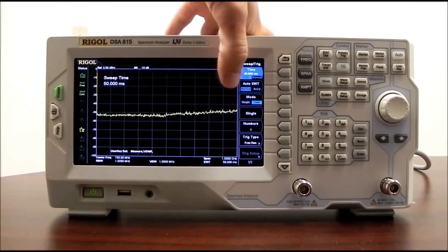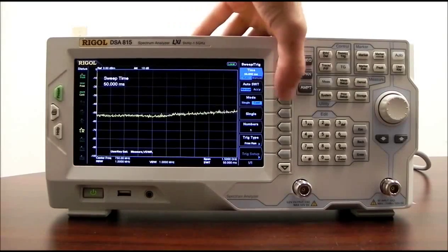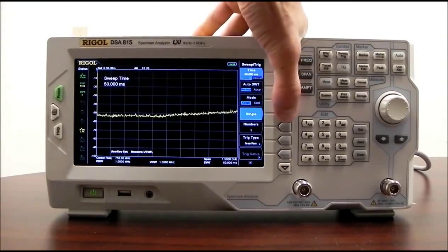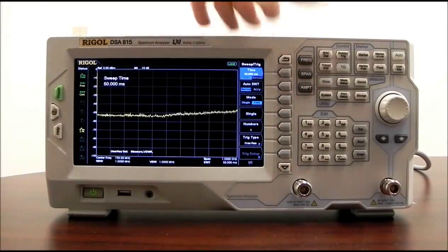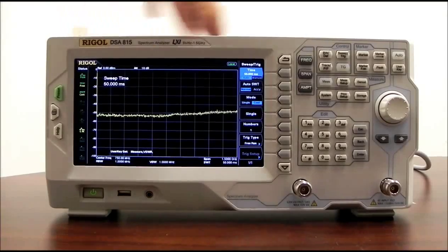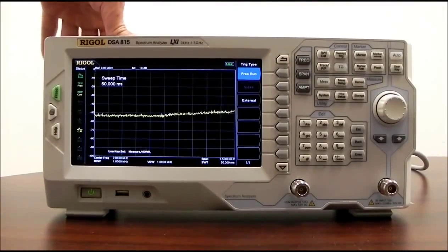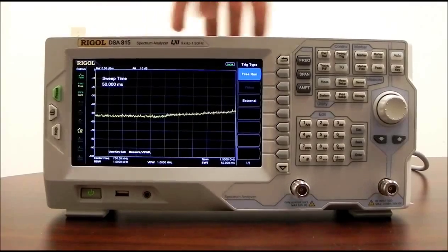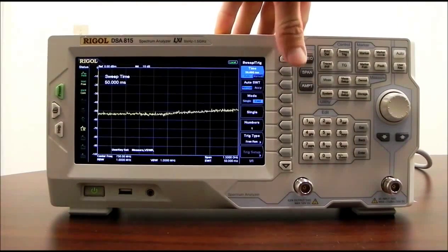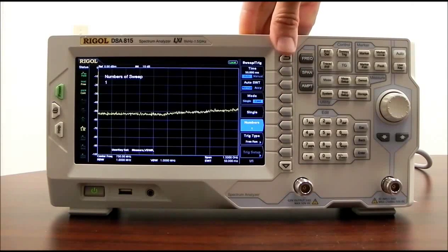We have auto sweep time. We want to keep that normal, or we can go to accuracy mode, and then for mode we can go continuous or we can go single, and with single we can just press single trigger if we wanted to capture one image. We also have the ability to do an internal trigger, which is going to be free run, but we can also do external. There is a BNC connector on the back, a TTL level signal, so if you wanted to trigger it in an automated way in order to capture images, you could do that as well. You can set the number of scans per trigger using the numbers key.